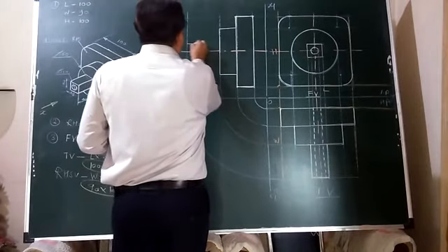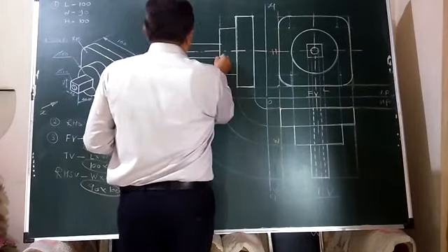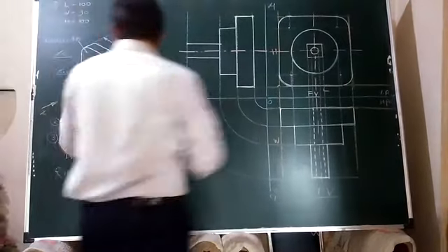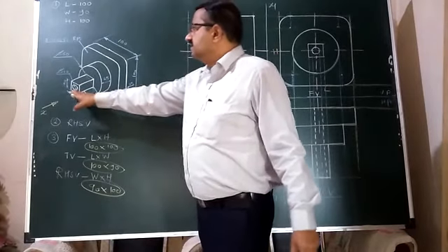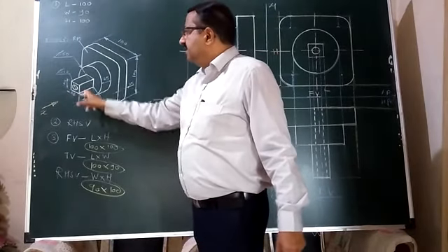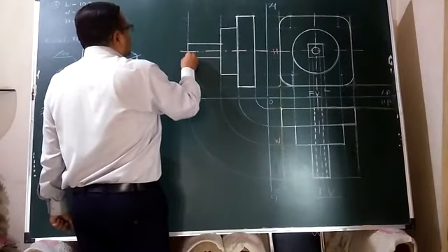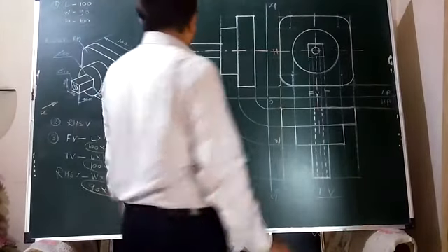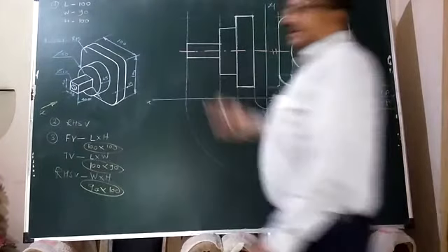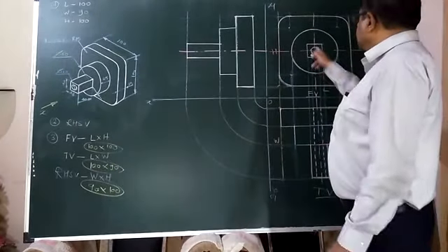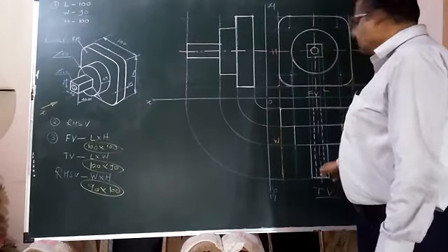Now this is nothing but its side effect of that. This square rod we can say, carrying 20 by 20 as its dimensions, that is length 20, height 20 and width as 40 mm, that will be fitted exactly at the center here. Again, inside, that cylindrical hole is also not appearing at all. This hole is only appearing in front view. In top view, it will be given reflecting its dotted effect.